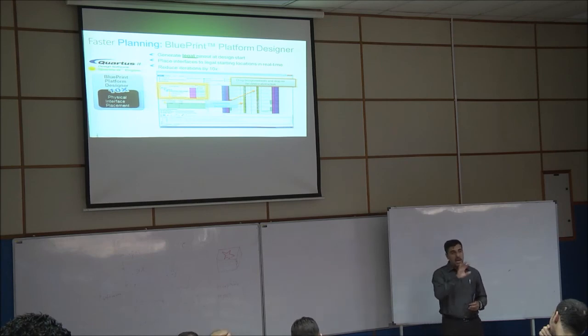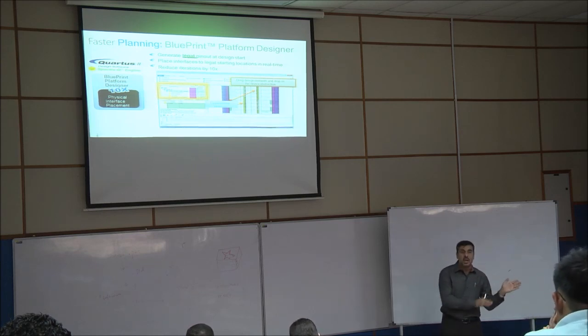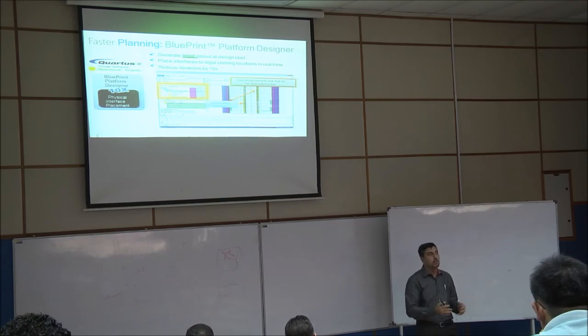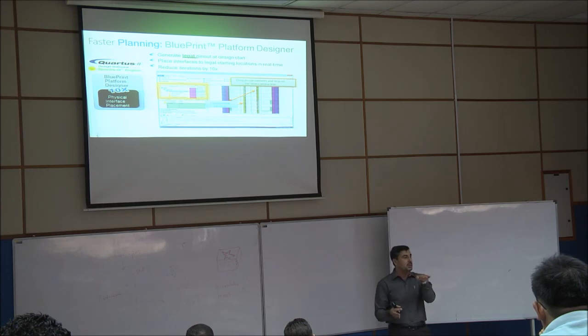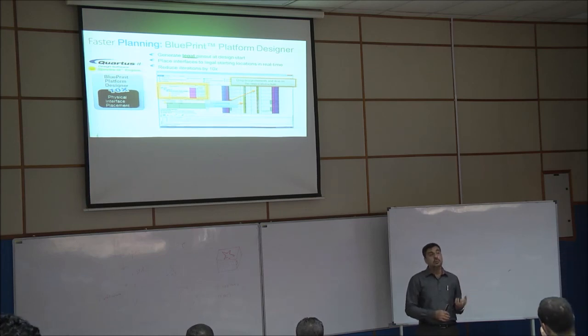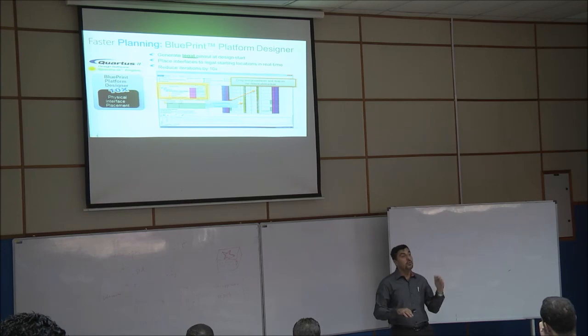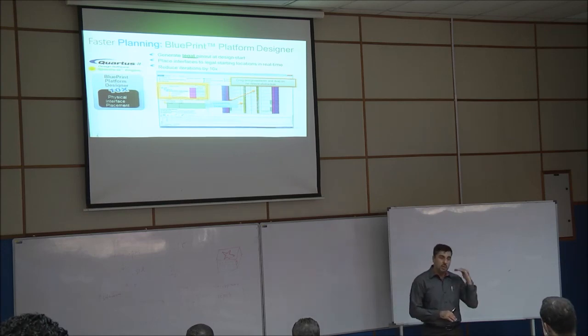Why? Because as we know, the FPGA has limits, for example, we cannot utilize 100% of the FPGA. If you want high performance, theoretically they say you can utilize all, right? Practically, I'm saying to you, until 80% of utilization, you are in good performance. If you go beyond 80%, your performance will go down, a drawback. That means, if you have 50K logic elements in your chip, and you utilize, for example, 30K, still okay. If you utilize 45K, that means your performance will go down.